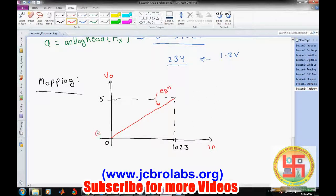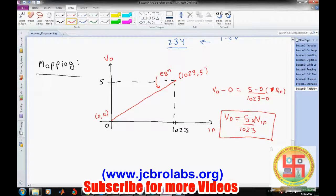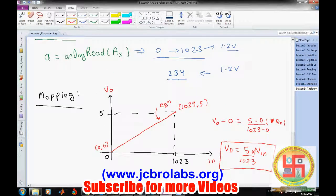The coordinates of this point are 0, 0 and the coordinates of this point are 1023, 5. So it is very easy. V out minus 0 equals (y2 minus y1) 5 minus 0 divided by 1023 minus 0, into the input code, whatever the number n is. So V out will be 5 divided by 1023 into the number or voltage, anything. Just by using this formula we can convert this particular number back into the corresponding voltage.